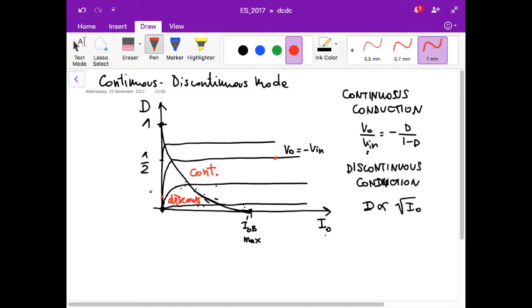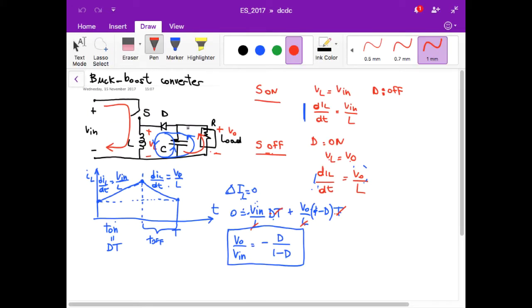To first order, the output voltage is constant. Now, in practice, what happens if we consider this converter? In practice, we have a ripple on the output voltage, and you can see it clearly because, if you look at this plot, during T on the load receives current only from the capacitor, and when the capacitor provides current, it is discharged. So it loses charge, which means it reduces the voltage.